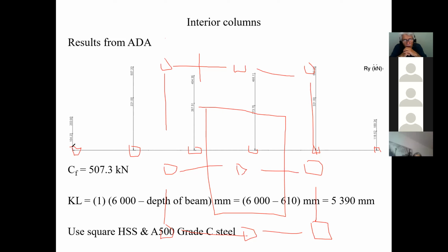Okay. Yeah. And if I'm not mistaken, if you remember way back when, I believe it's a load case where you put 100% here, 100% here, and 50% all the way along. That gives you the highest. I'm trying to remember which load. It even tells you which load case is going to give you the highest value, but you don't have to worry about that. You just go to your envelope and you get your values.